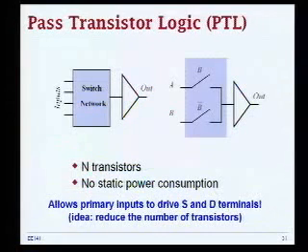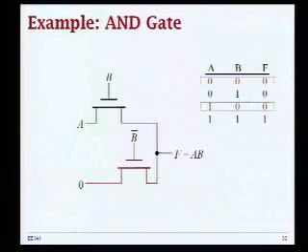So what you have in pass transistor logic is a switch network, which implements your transistors as switches, the pass gates. We've seen this structure in the previous lectures, so it's familiar to you. You have gate signals controlled with certain voltages, and then you have source signals as well. So here's an example of an AND gate.